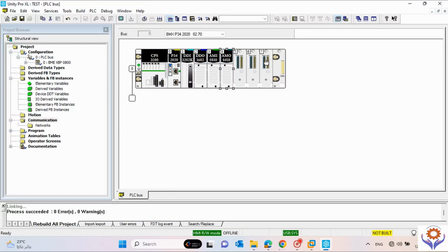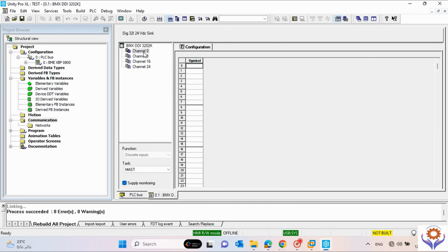Okay. So the address format for any PLC, first of all you need to understand the IOs. Here, if you click, you have an example: if you have a 32 DI card, it will be divided into 8-channel groups. See here, 0 to 7 is one channel, 8 to 15 is another channel, 16 to 23 is one channel, and 24 to 31 is another channel. So it will be divided into 4 channels, and you can select each channel also.